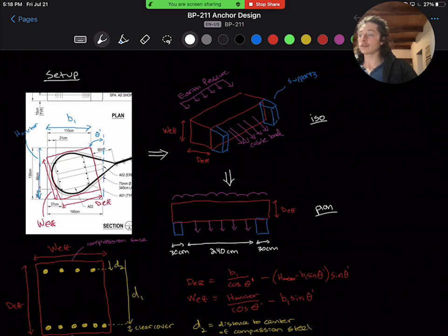The plan view shows the unbraced span of 240 centimeters, and a quick note here, eventually the fill does partially brace the anchor, but if you remember from the ramp wall lectures, the masonry walls are stiffer than the masonry fill. Because of this, load will first transfer to the walls, and only to the fill after the beam begins to bend and potentially crack.